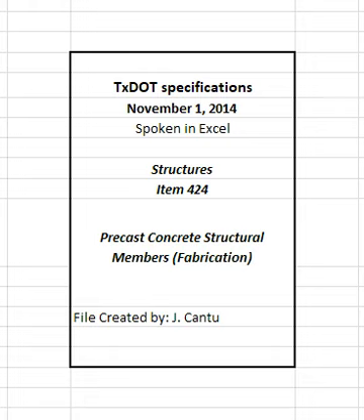2.4 Batch plant. Provide batch plant on-site for SCC construction unless otherwise approved. Do not use volumetric mixers for SCC. 3. Materials. Furnish materials in accordance with Item 425, precast prestressed concrete structural members, and other pertinent items. 4. Construction. 4.1 General requirements.